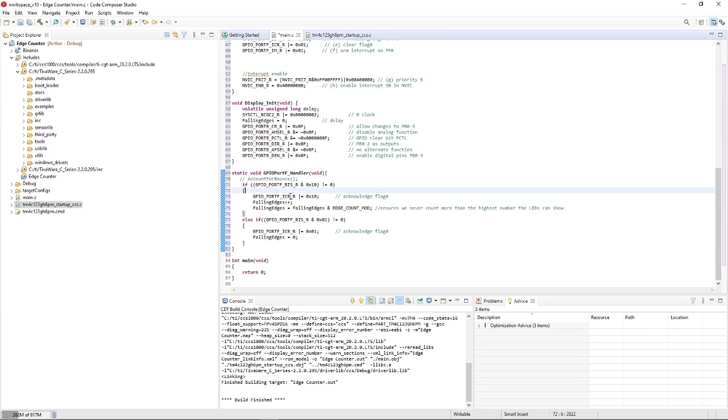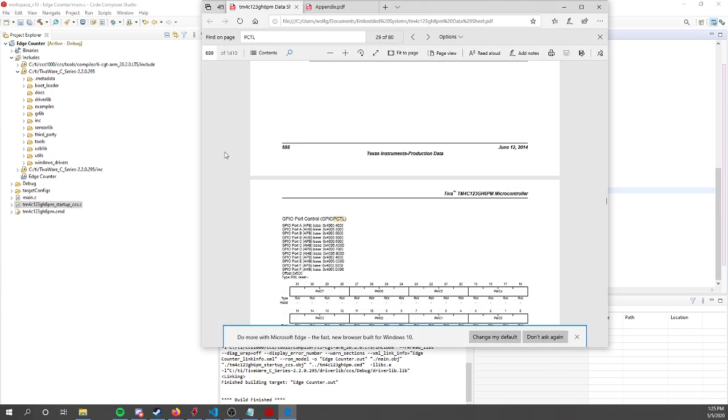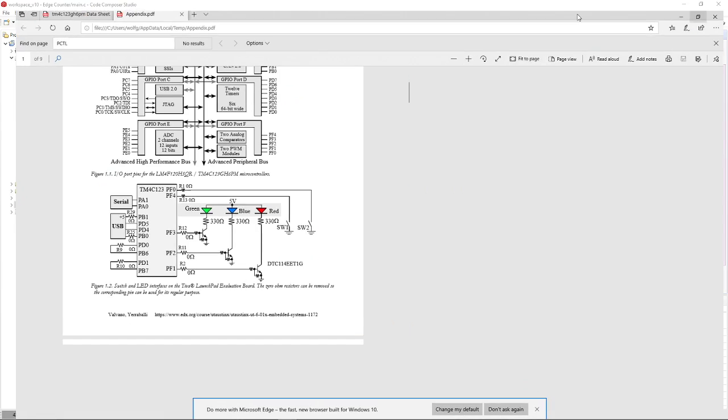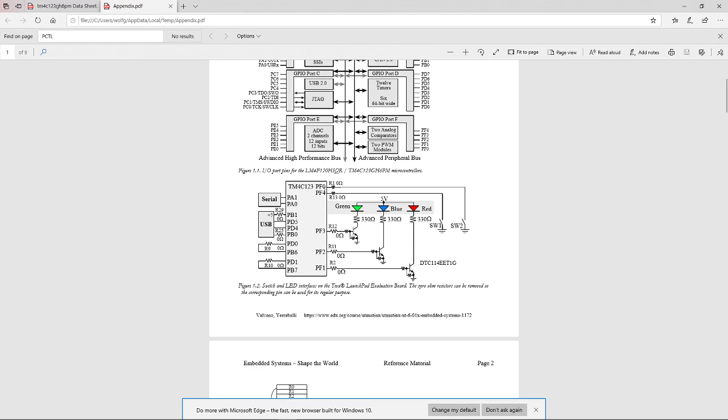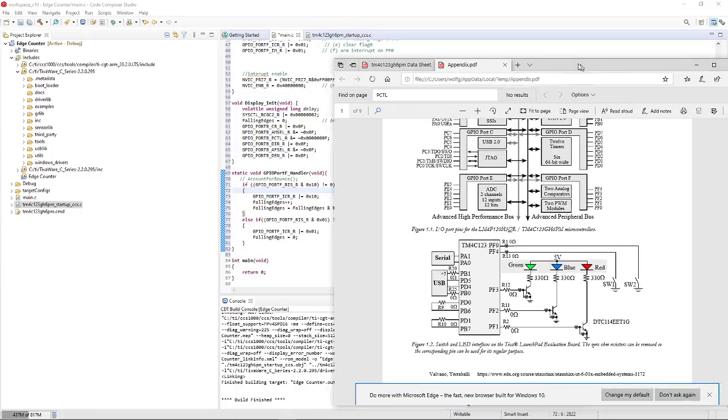That is the raw interrupt status register. It is a very interesting register where basically it is just a bunch of bits saying that whenever you have an interrupt, the specific pin sets its own bit. So when we press switch 1, we go back to that diagram. When we press switch 1 on here, it sets bit 4 to 1 in this raw interrupt status.